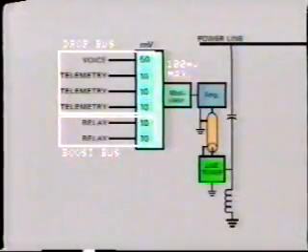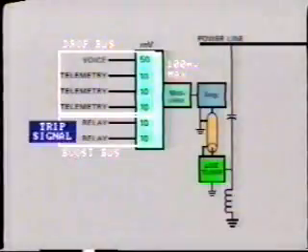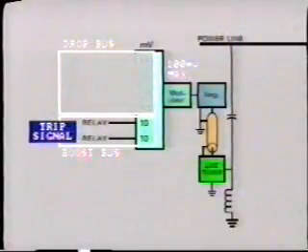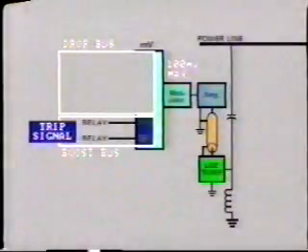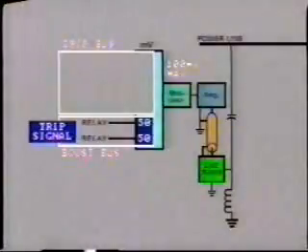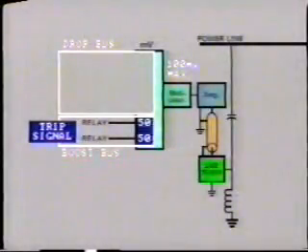Now, when a protective relay sends a trip signal through the tone equipment, this contact initiation also disconnects the drop bus from the modulator. At the same time, the boost bus modulation voltage is increased to 50 millivolts for each relay tone. We have now increased the important line relaying signals by a factor of 5 at a very small cost.